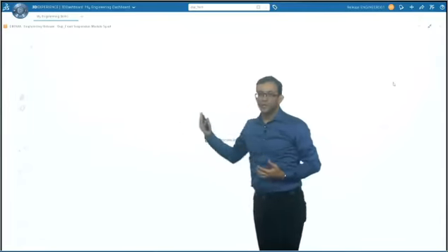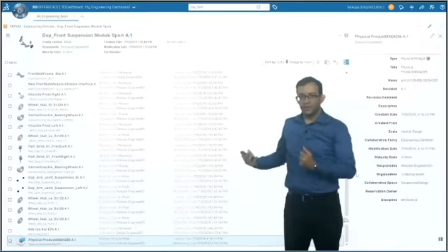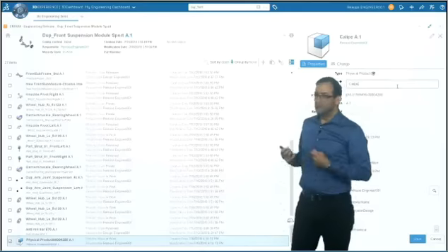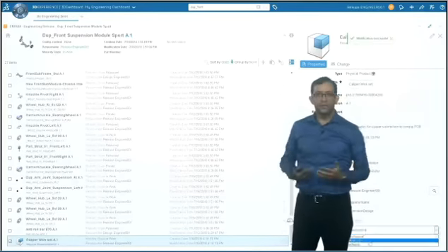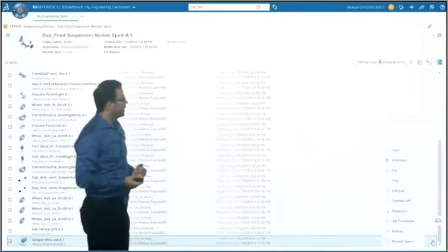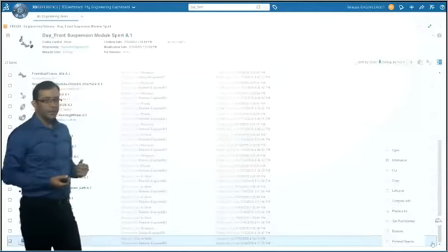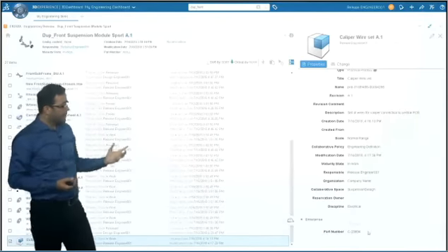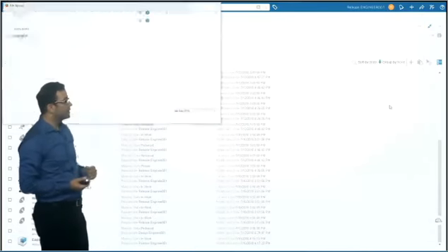And I can start defining which of these engineering items will be part of engineering change, which ones I'm going to modify probably manually. And what is important also is to make the decision here who's going to be owning those components, those engineering items, in terms of the designers and those engineers. So I do this through a change ownership. And I can set also a part number, and that will be the part number that will be available later on in the ERP system. And once it is available, I can see it here directly in the attribute, directly on the engineering item.